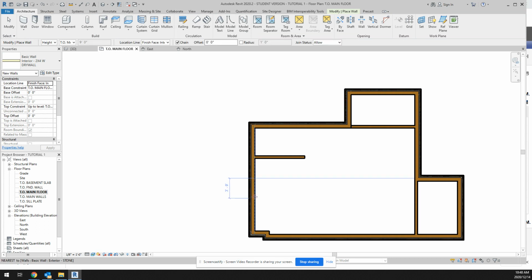So say I had 2 walls coming off of this. Well, if I'm trying to decide how long from inside to inside here needs to be, if I haven't calculated all that, you need to figure out that I have this room, which may be like, say, 10 feet. Then you have to account for your 4.5 inches or whatever the thickness of your interior wall.